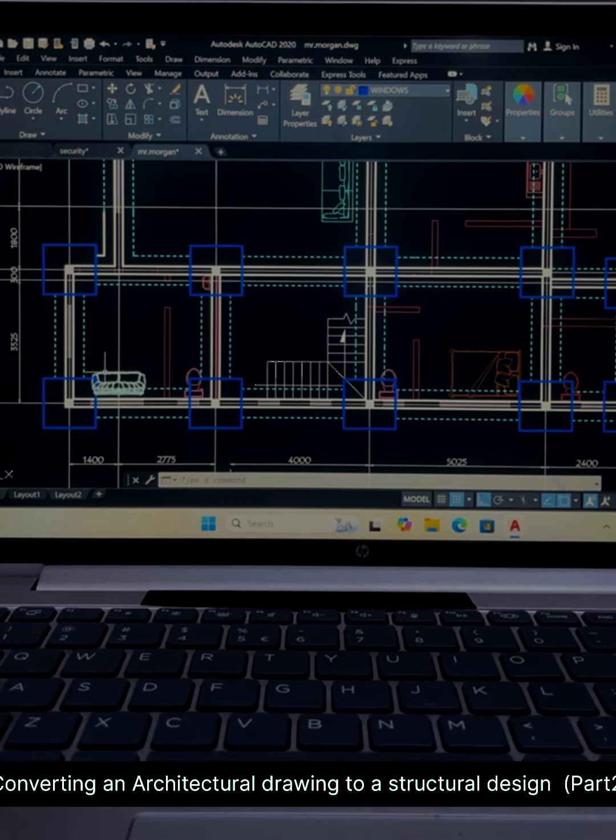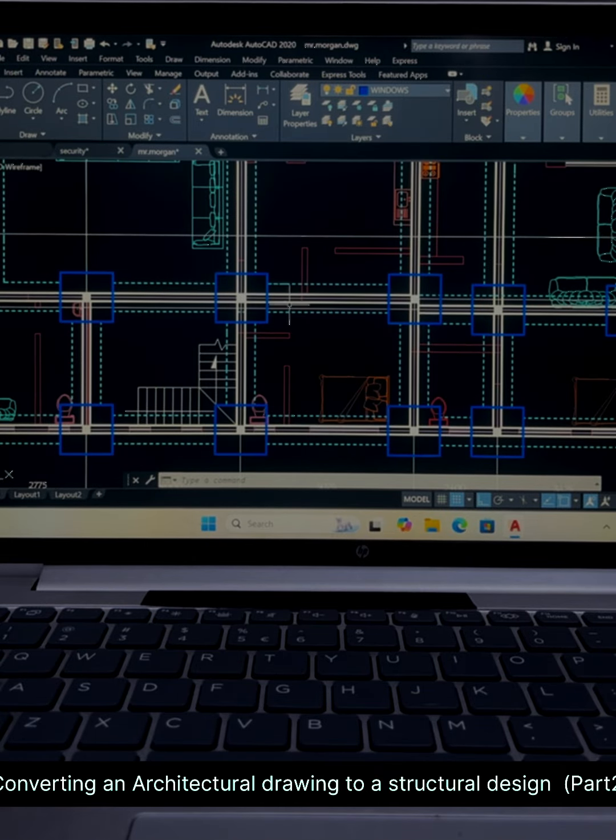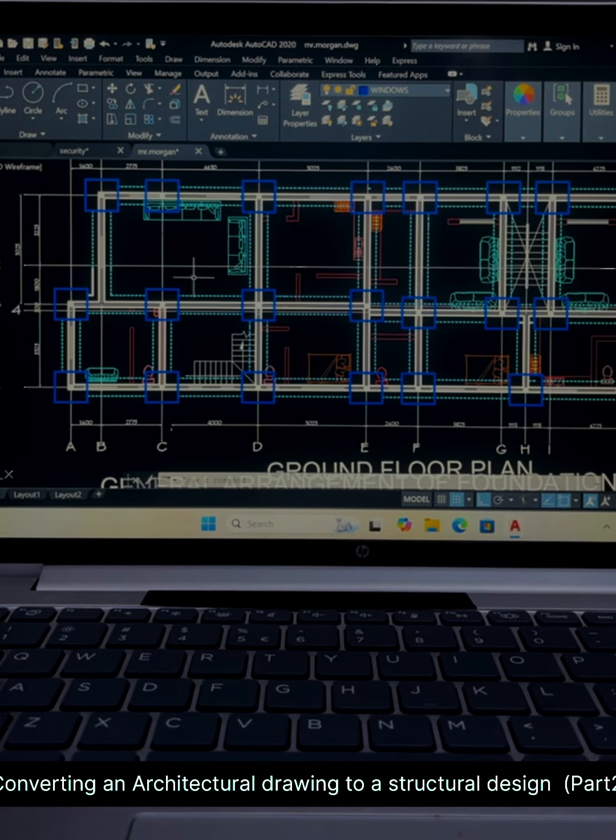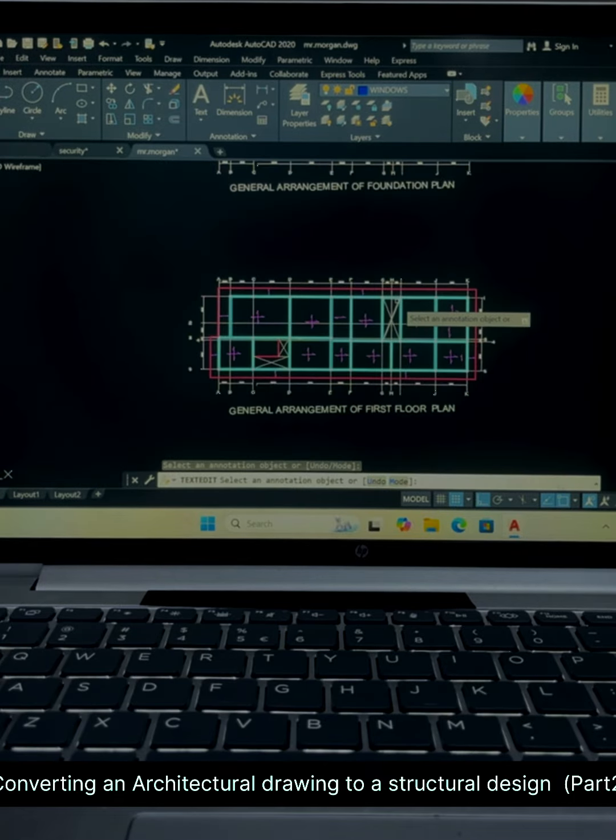That is the design to take it and every other thing. You spread the wall load on the ground floor slab. So typically this one passes the general arrangement for the foundation because, one, the columns are embedded in the walls and every other thing seems good. So we can now go ahead to look at the general arrangement for the first floor plan.